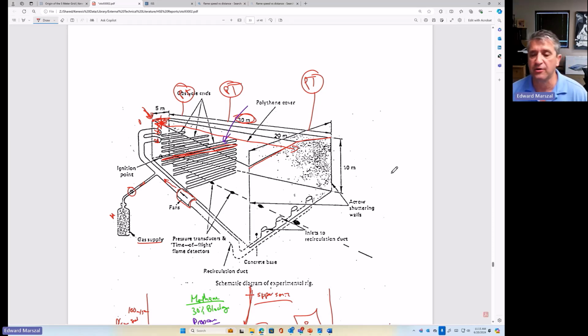When you're doing geographic coverage, and we at Conexus don't recommend geographic coverage most of the time unless you're worried about accumulations. If you're worried about detecting releases, you should really be using scenario coverage. But if you're going to use geographic coverage, the key parameter when you're doing your risk analysis is what is the critical gas cloud size.